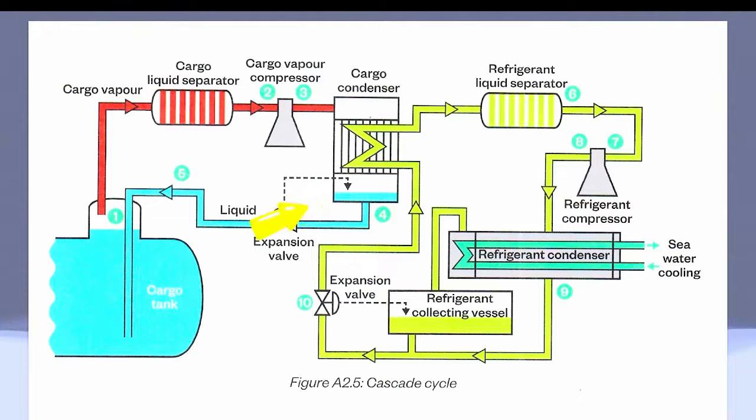After that, the liquid flows through the expansion valve. The process of throttling then begins to occur. Consequently, the pressure drops, the temperature decreases, and the now cold liquid returns back to the storage tank by traveling through the condensate line. We are cooling the cargo, lowering its temperature by removing vapor. These are vapors. And the more quickly we do this, the faster we can cool them all down.